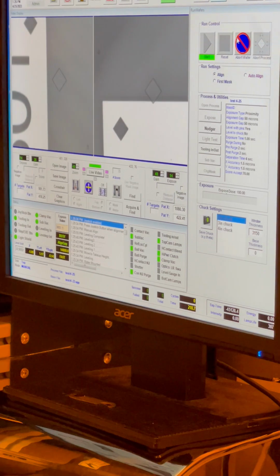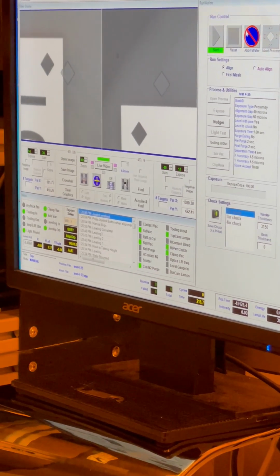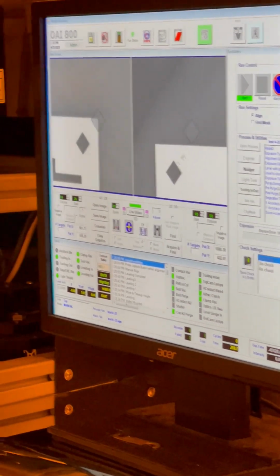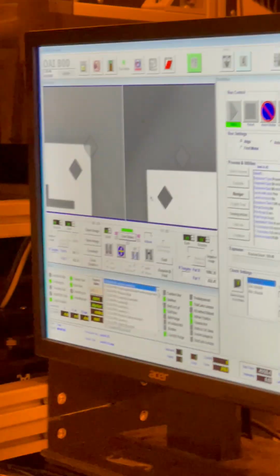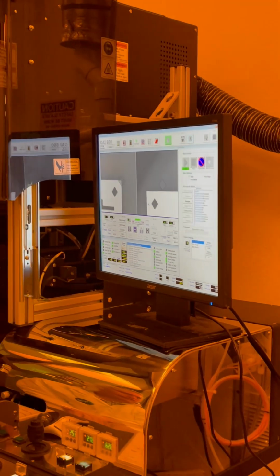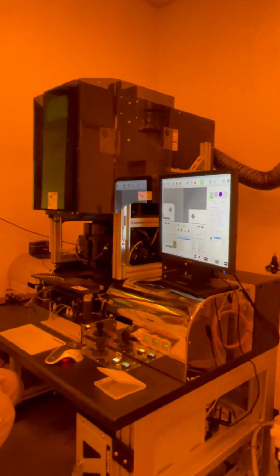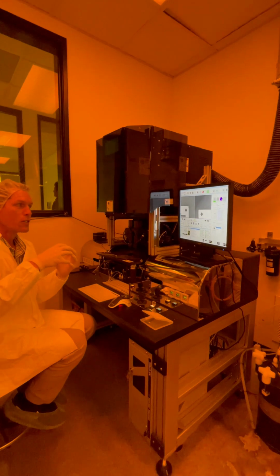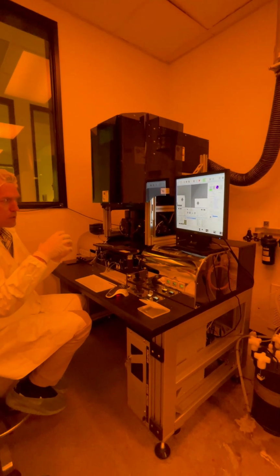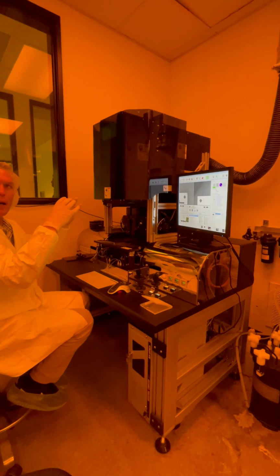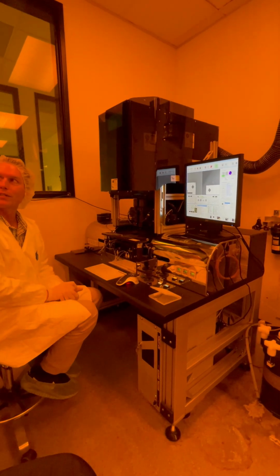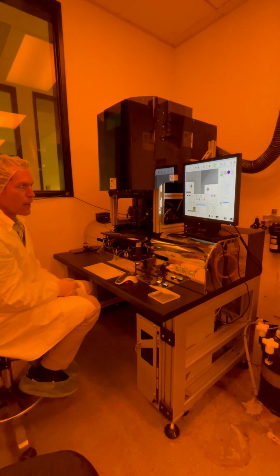Yeah. There's one. Now, Raynard, their targets, they do a manual align for some reason. I don't know why they're doing it that way, but these targets are really, I don't know if you know anything about auto alignment machines. A little bit. But these targets are not ideal for auto alignment because they overlap, and so that confuses the computer between which one is which. Right. So ideally, you want one being completely around the other one with no overlapping lines, so it can see the edges. 4 boxes and a cross or something. Something like that, yeah.